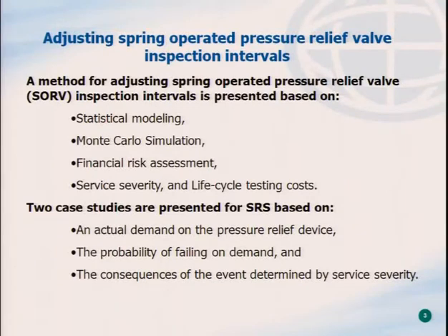The thing about the data that resides in our database is we do know when the valves are installed, we do know when they're taken out of service, and when we conduct a test on them, we know that they've passed or failed, and we record the pop pressure. But we don't know exactly when the valves have failed. The paper that we presented this morning concentrated on a root cause analysis, engineers disassembling the valves that have failed stuck shut. Stuck shut would be a pretty serious failure if in fact the valve were initiated, and that the ratio of test pressure to set pressure is 1.5.